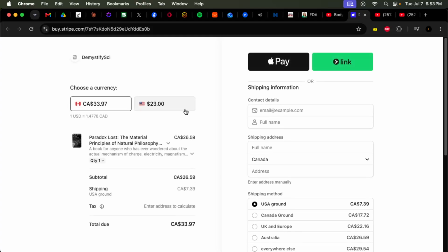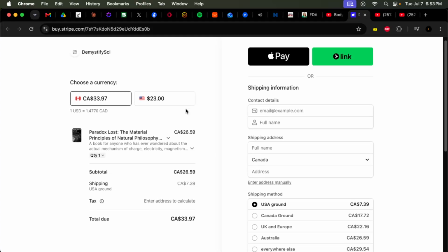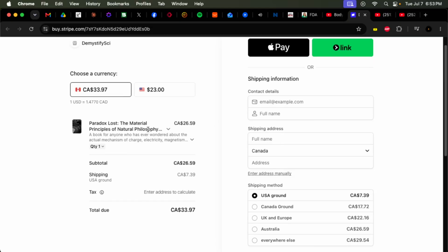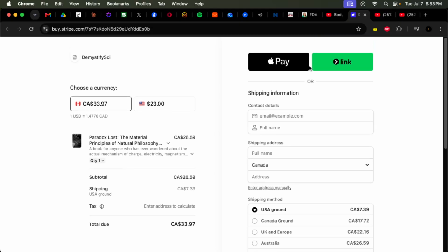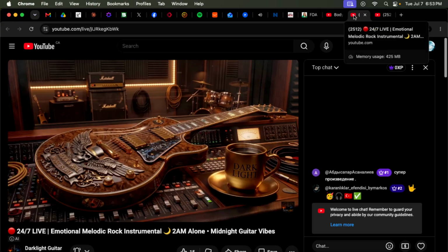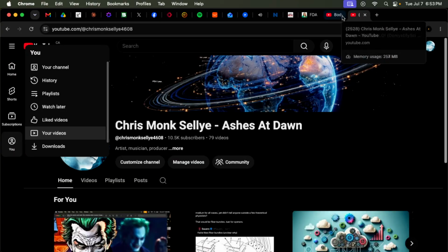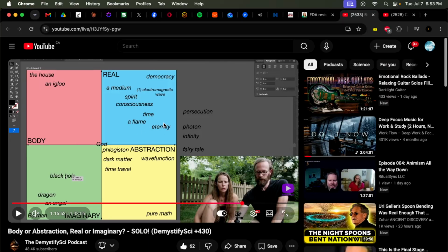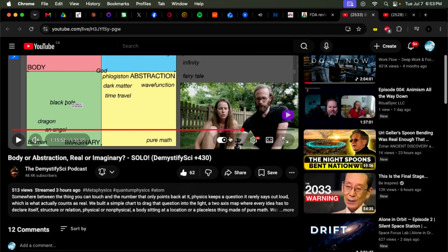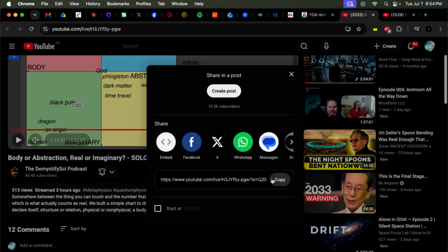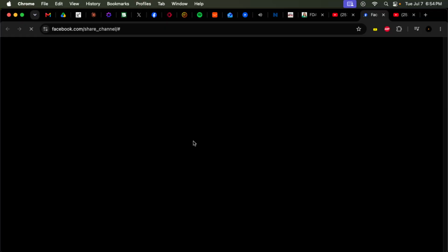Third, and most directly relevant to the energy claim, a full energy audit of one complete write, transmit, detect, and re-emit cycle, measured in joules per bit updated, can be directly compared against the energy per bit update of a conventional electronic memory cell fabricated in a comparable process node. If that measured figure comes in below the electronic comparison, the excluded status assigned above should be revisited. We regard this as the single most important experiment to run before any further version of this document is prepared, since it directly tests the claim most likely to draw scrutiny from reviewers.